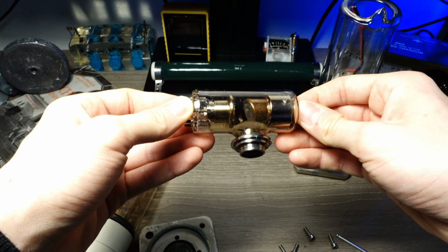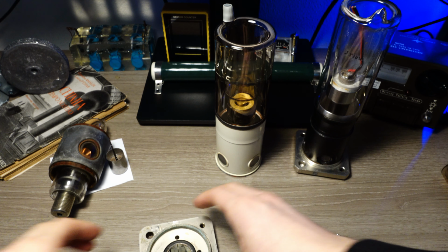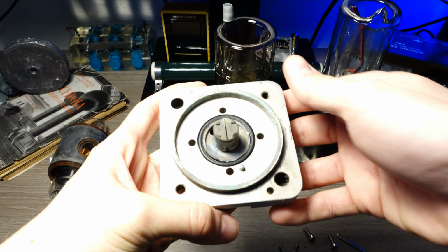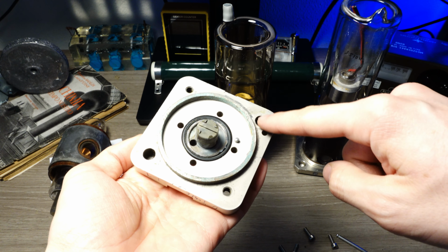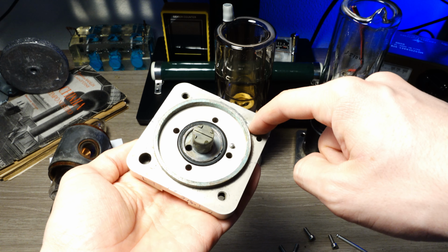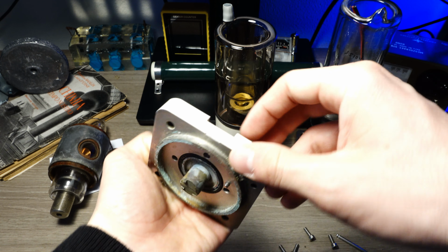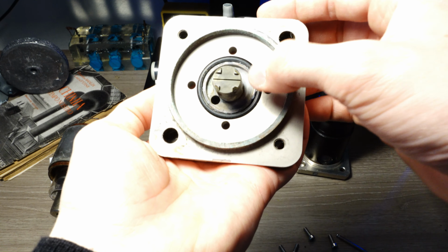So here you can see that the anode is this part inside, and is cooled by a constant stream of water that is injected towards the anode by this plate. So you have that here, and here there's the water supply, so water comes inside here and enters through this thick metal part and exits here in this slot.